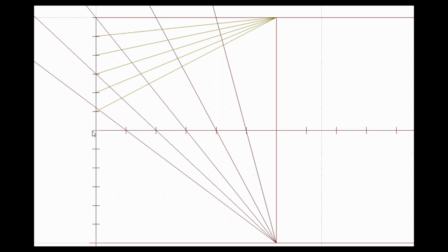So the quarter of the ellipse would essentially pass through these points: point 1, point 2, which is the intersection of these two lines, this line and this line. Then we have this one, and this. Now let's draw a freehand curve through these points, which will give us a quarter of the ellipse.